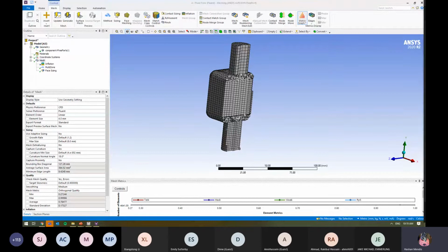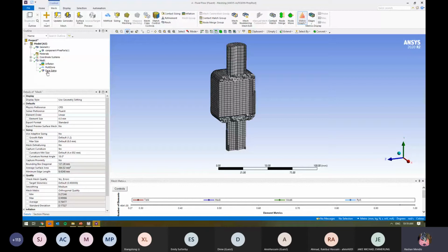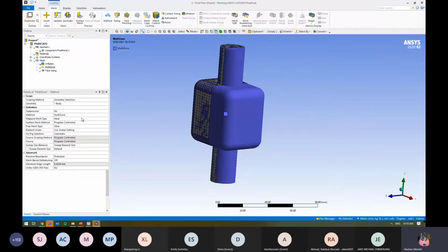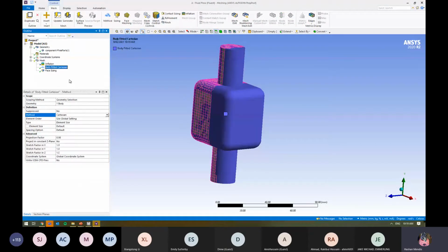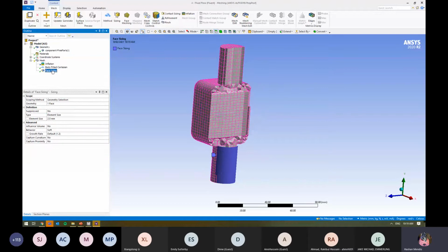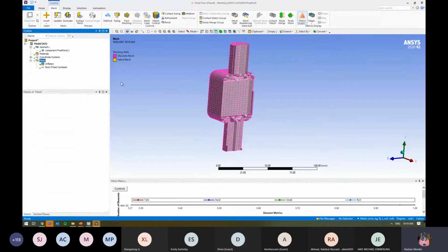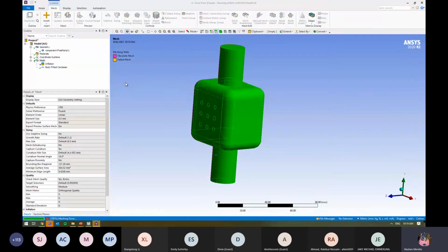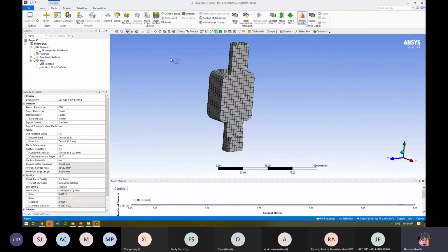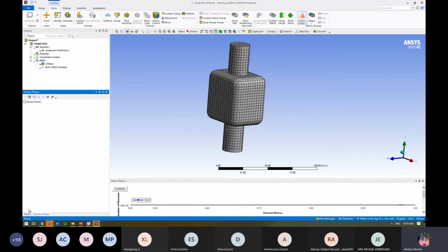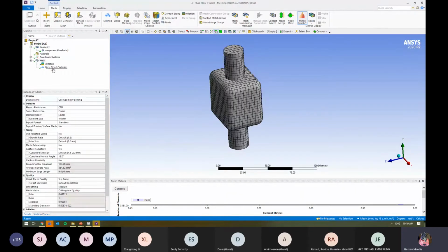Is hex dominant okay for simple cases? Yeah, simple geometries where you're not too fast. If you've got a large thing, hex dominant's okay, but we always recommend don't really touch it. Stick with multi-zone if you can, because you're going to get better elements everywhere. There are also things like a Cartesian option, right? This Cartesian option might be good if you have 3D printed components, where it will try to just put a Cartesian mesh everywhere, or if you have things like STLs as well.